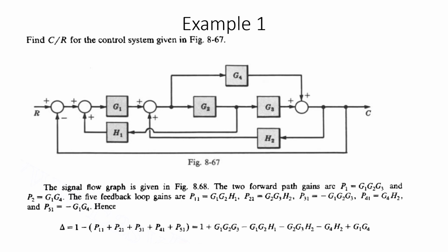So let's take the first example. This is a block diagram which is given to us, and the task is we need to find the transfer function for this particular block diagram. Now the first step is, as usual, I have explained this also in the previous session. If you want to represent any block diagram in a signal flow graph representation, the summing points and takeoff points should be replaced with nodes. So replace the nodes and then start writing the signal flow graph for this.